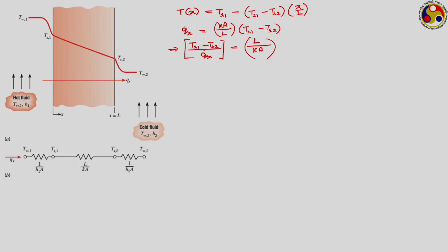In the first week itself we have introduced the concept of thermal resistance. So, can you relate this one to this? On the left hand side we have the potential difference in the numerator and the effect of that in the denominator, and we can easily relate this to Ohm's law of electricity, where we can easily write, suppose E1 minus E2 refers to a potential difference between two locations 1 and 2, then the corresponding result will be equal to current I into R,